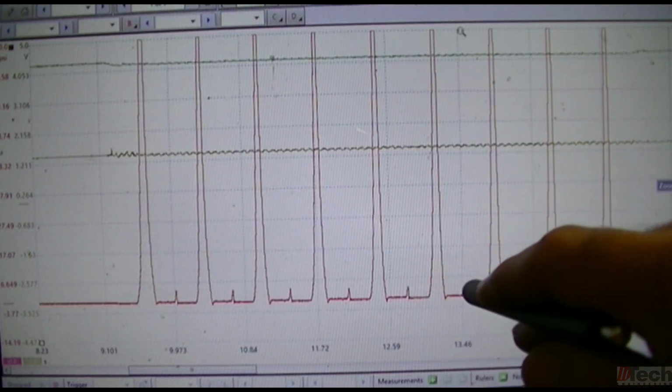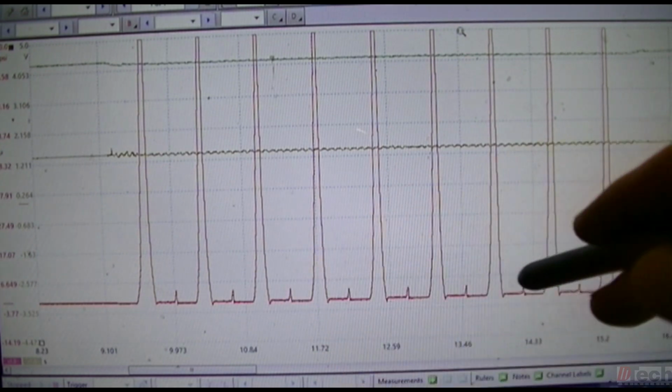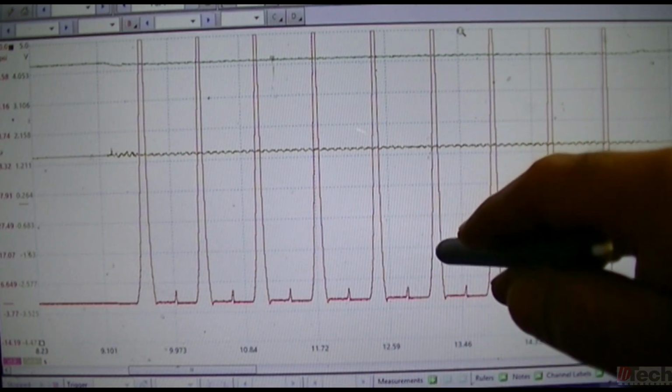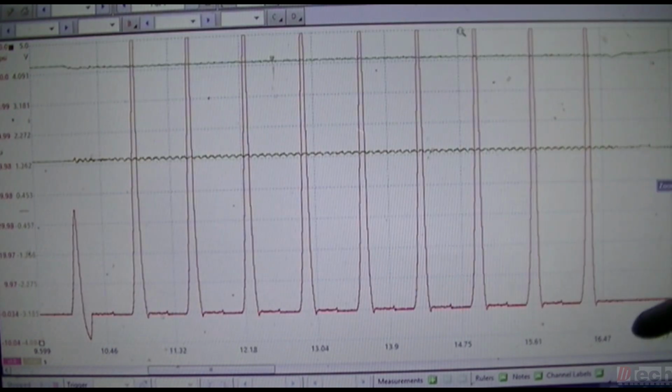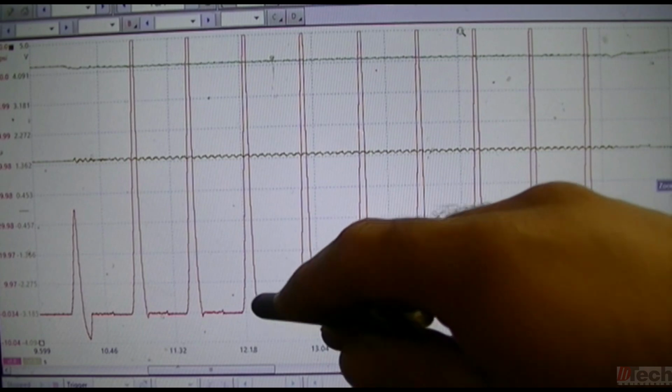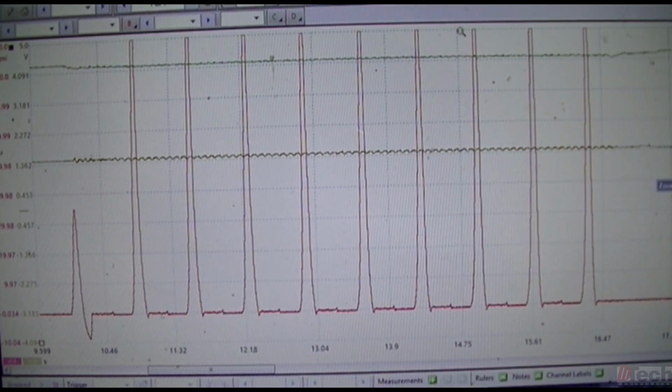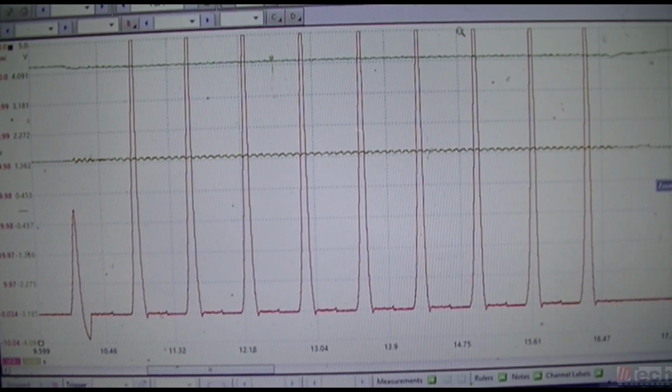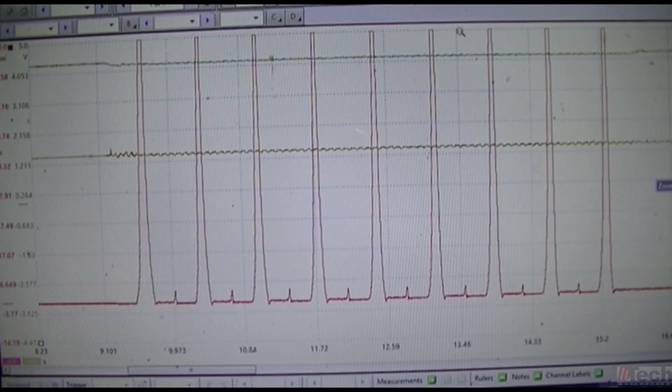You're seeing this rise in pressure in between the TDC points that is higher than the rise in pressure in bank 2. And right away, just during cranking, its breathing bank to bank is already different, due to what looks like it can be a timing issue bank to bank, which would correlate with the code as far as the bank.